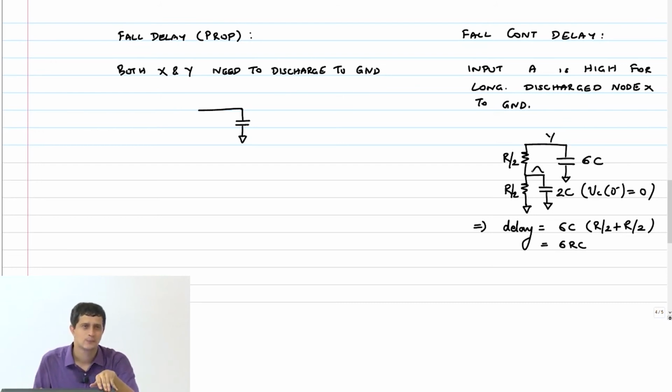Okay. So her question was, if this capacitance was already discharged to ground, that means the VDS of that bottom NMOS transistor is 0. So how can you have any current flowing through that? So she is right, because to accommodate some current, the VDS has to bump a little bit, right? Only then you can have some current.